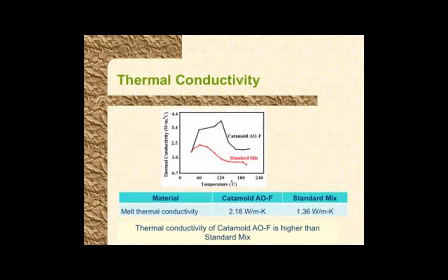Conductivity. If you have more metal particles, you're going to have higher conductivity. The part is going to solidify more rapidly. So knowing the thermal conductivity of the mixture becomes important, and being able to model it as a function of concentration of powder becomes important, because then, just like viscosity variations give a measure of homogeneity, thermal conductivity variations or electrical conductivity variations will also give you a measure of homogeneity.